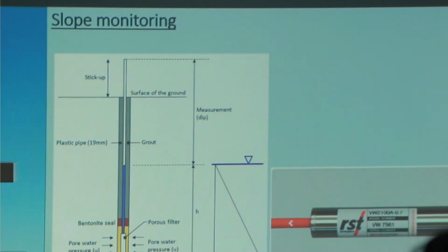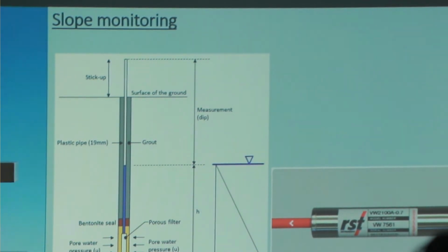And the most effective thing in pore pressure measurement is, let's say, in a soil slope, when we already know the slope and the shear plane. Then what we can notice in the pore pressure is if there is shearing or acceleration in the movement, we can feel the acceleration in the pore pressure generation. That's how we get the information from the piezometers.